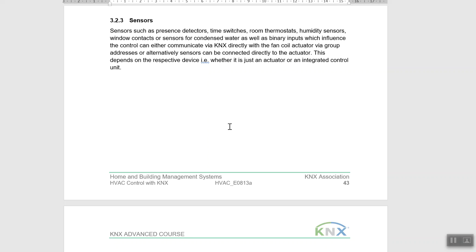Please note that when controlling the fan coil unit, the simple setup is a thermostat with temperature sensor inside and a fan coil actuator to control it. But sometimes we have more items: digital input outputs, analog input outputs. Maybe we want the fan coil actuator to act based on humidity, to reduce or keep the humidity at some level.